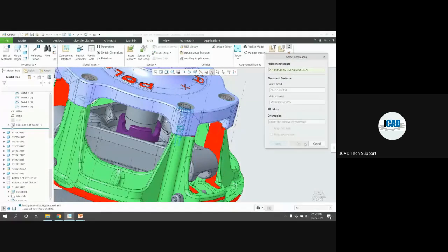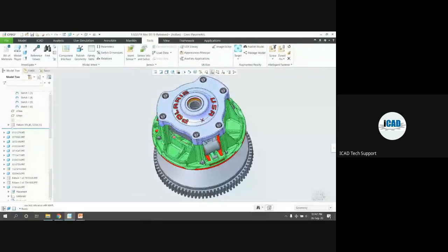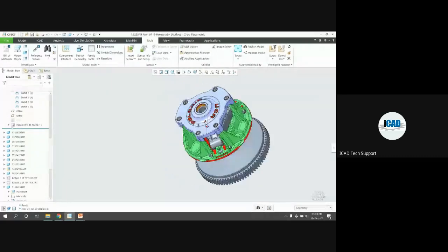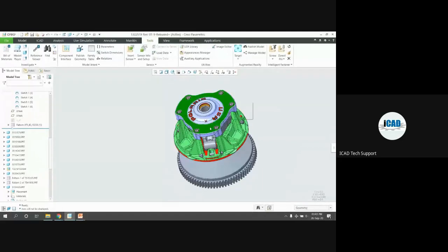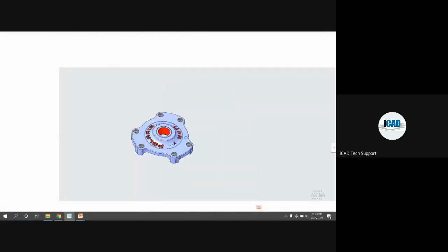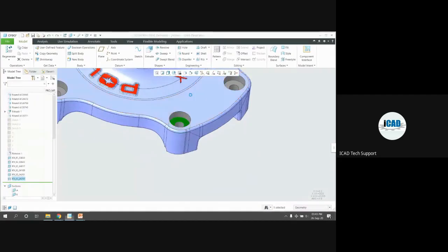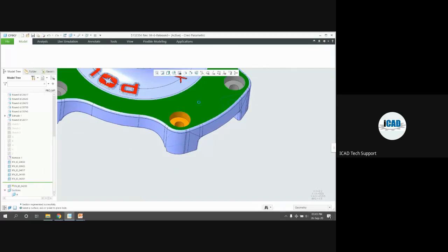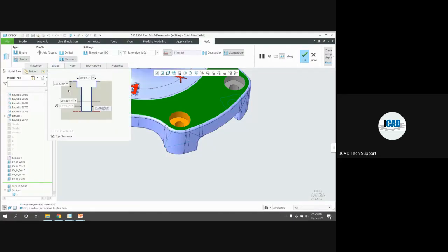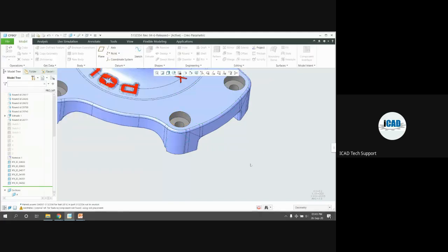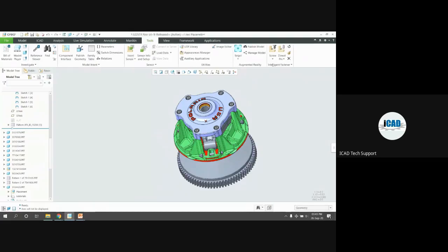You can see, click on the cancel button. Now you can see this is very quick. We can assemble those fasteners on our assembly. So now if I am just cross checking, these holes are created as per the standards. You can directly edit from here also for the cross checking. You can see the M6 by 1 size automatically gets selected. Clearance, shape, you can observe medium fit clearance. The thread size and depth size automatically get captured from here. Just click on cancel. So this way, this is the intelligent fastener extension.